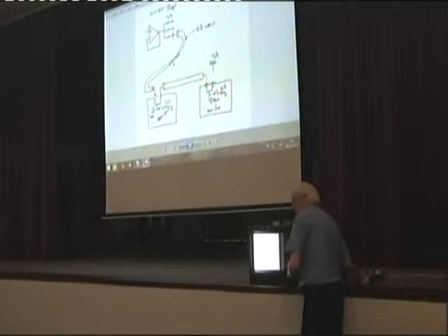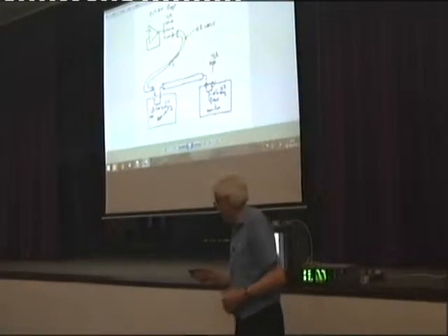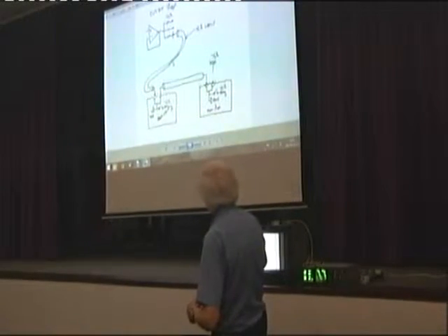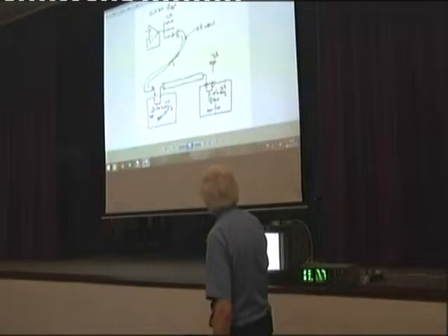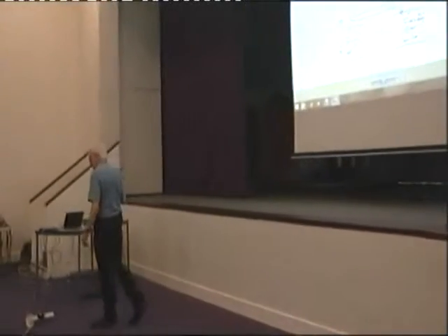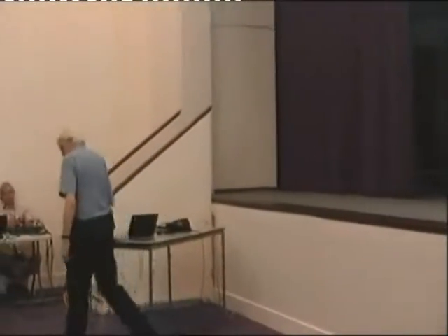Well, that bit of coax is a transmission line. Signal going down there that is unterminated or incorrectly terminated will be reflected back up the cable. It's like SWR on your aerial in a way. And if you're unlucky and that bit of wire is an unfortunate length, the reflection is exactly 180 degrees out for subcarrier and it cancels it out.